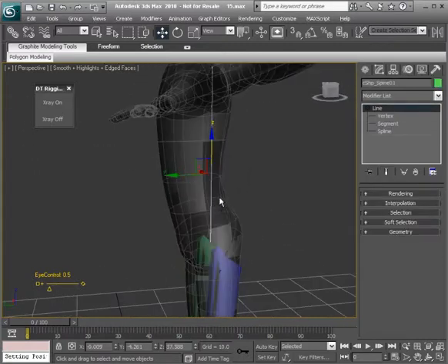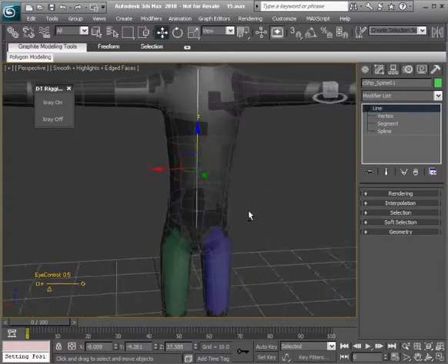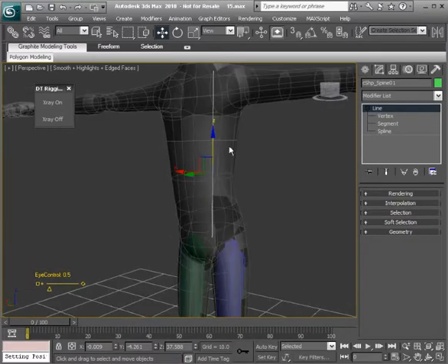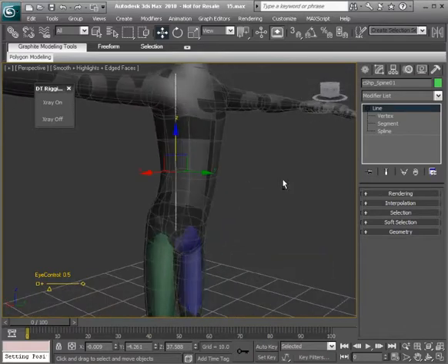Great, now that that's done, we're going to rebuild this curve so that we can have an even spacing of vertex ticks. Now, the even spacing is going to allow us to modify this curve's flexibility to our liking, so we can get it functioning the way we need it to very quickly.